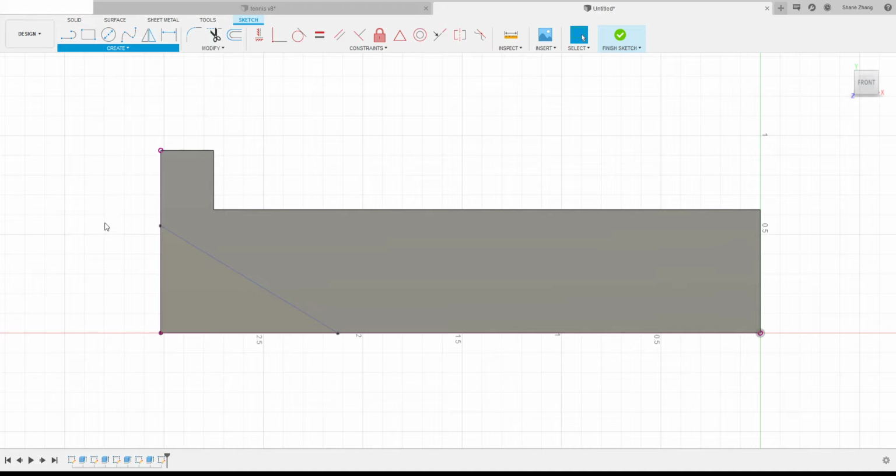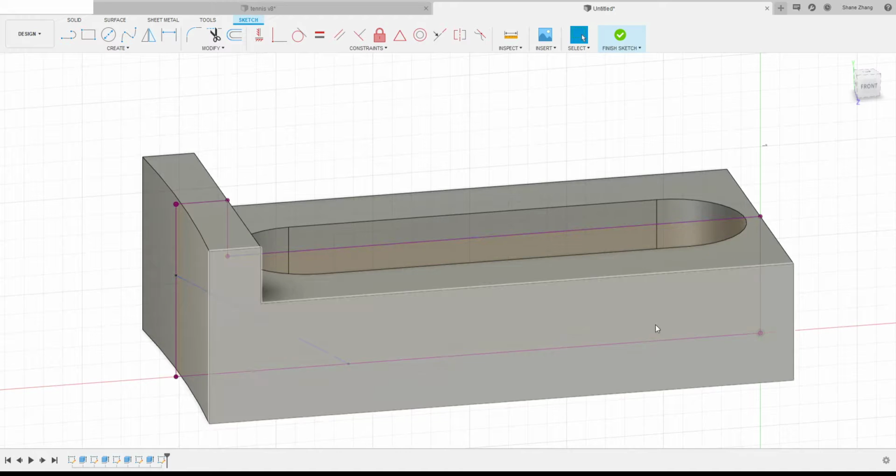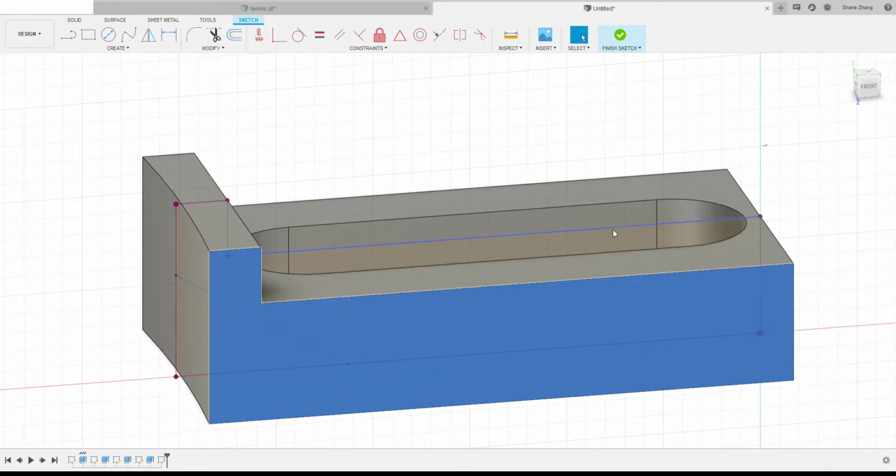Let's find out. Project and include. So project this shape into your sketch, because this shape right now is outside of the sketch plane. So we'll do a project. We'll pick this plane and say OK. Now you can see all the dots, or you can actually see there's the lines created from this plane, and that projects into the sketch plane.